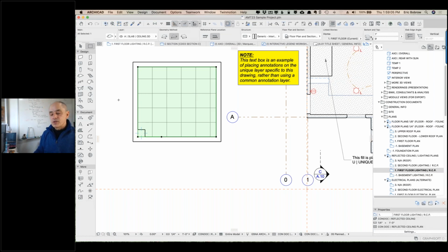So how would you do a more sophisticated version? I'm not going to demonstrate all of this. I'm just going to mention a few ideas. So one idea is that you actually draw these lines with little beams. So the beams can be just purely little tiny rectangles, or they can be a profile shape, the T bar that supports the acoustics. And you can draw one and then multiply it every 2 feet, and fill up the space in each direction. You can also create or place individual squares of just this slab and drag copies or multiply copies to create a whole bunch of little ceiling pieces.